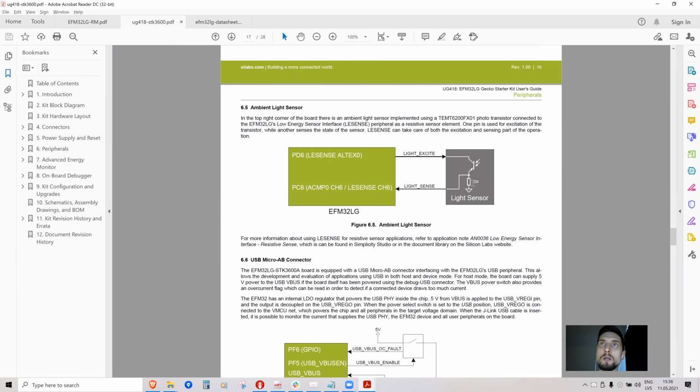Basically, there's a resistor and the transistor, and in the simplest form, it works like a switch. So when the light shines on this transistor, it conducts electricity, is like a short circuit, and this resistor has full voltage on it. So it will be the maximum voltage. And when you remove the light, this transistor stops conducting, and this resistor pulls the input down to ground.